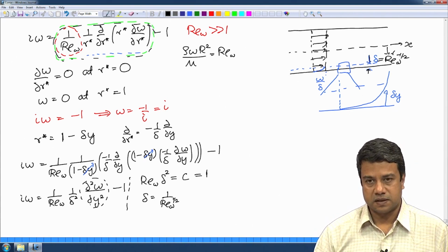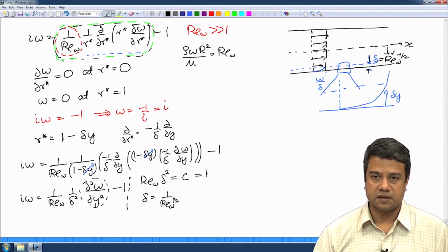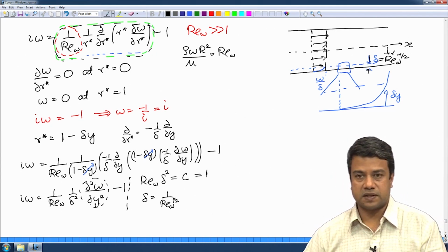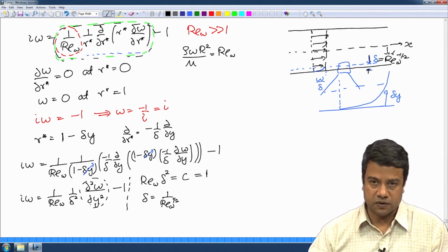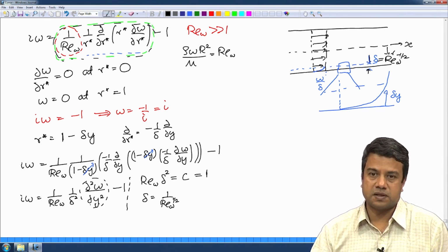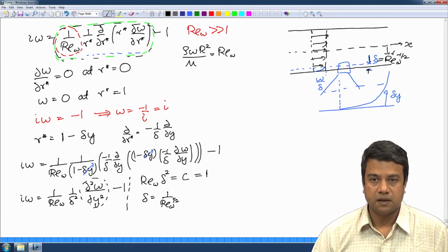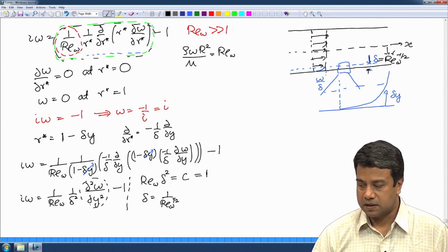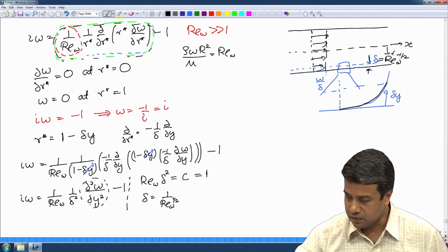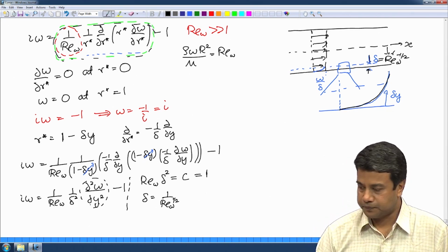That small distance is much smaller than the radius, because the time required for the pressure to reverse is small compared to the time for diffusion to the center. Diffusion takes place only to a small distance close to the wall. Within that distance, the velocity increases from 0 to the bulk value.